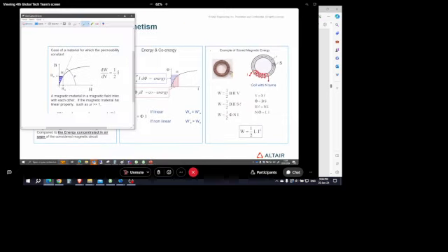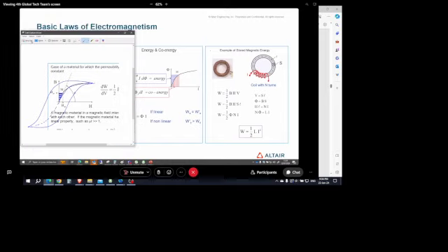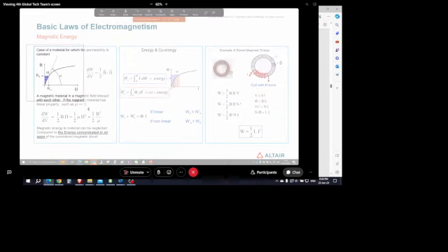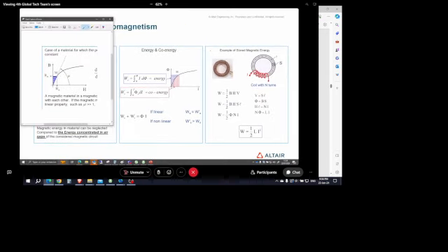And finally, normally we are going to talk about hysteresis cycle, right? So this curve is really what we call intrinsic curve. And the magnetic energy is actually contained inside the hysteresis cycle. So then here is the magnetic energy on the characteristic BH is really the area of this surface, right?